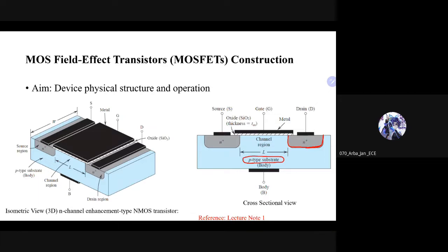You cannot have P type wells here, so you have N type wells. तो एक वेल यहाँ है और एक वेल दूसरी साइड से है. And it is N type. It is also marked as N plus. N plus would mean N but highly doped. Plus means highly doped N type semiconductor.